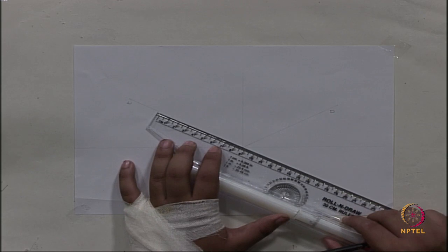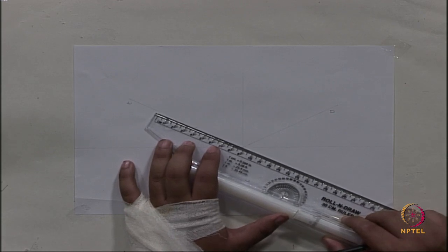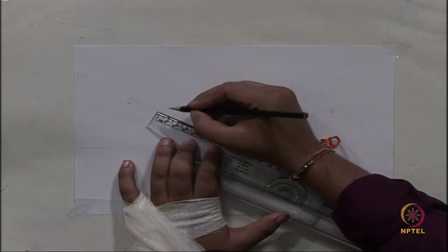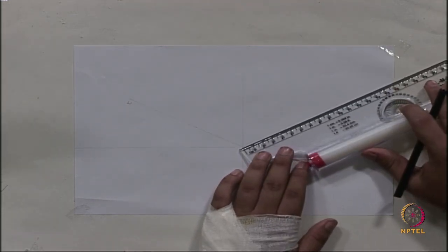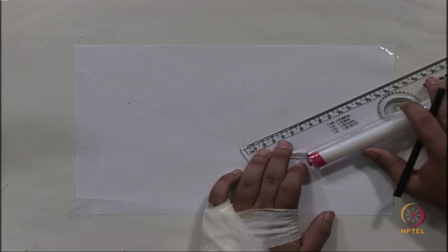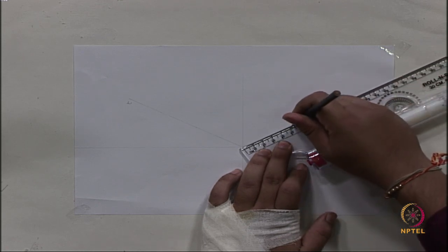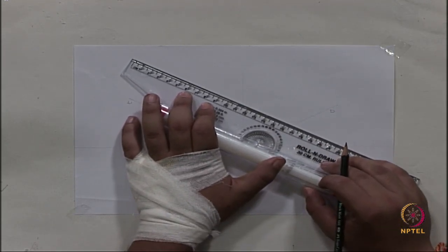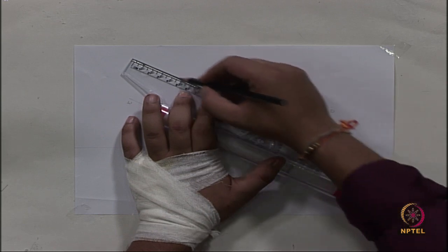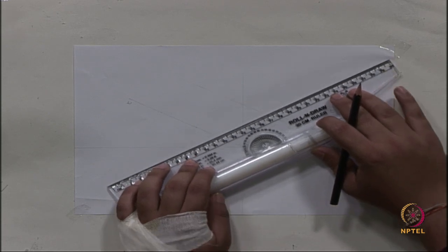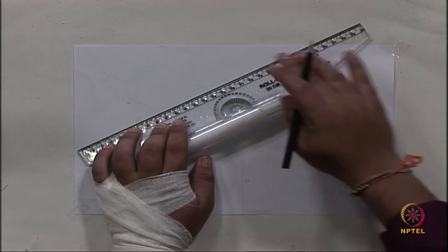Okay. To draw the rectangular base of this slab, I will first mark 88 and 54. This is the dimension of the base of the rectangular slab or cuboid. After marking these dimensions, I will use the parallel lines and connect these parallel lines to get the rectangular slab. These all are construction lines, so these all should be light and thin.